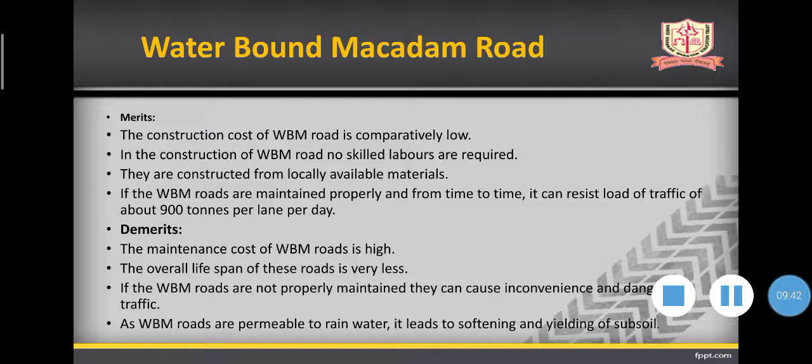So obviously the maintenance cost is going to increase, because the water will go under our road, into the different layers, and then obviously cracks and deformation of the road will form. Therefore, the maintenance cost of WBM road is going to be very high. The overall lifespan of this road is very less. As the deformation carries out, obviously the lifespan of this road will be very low.